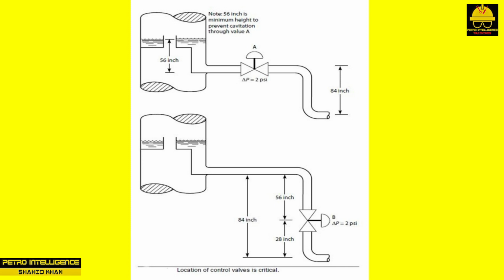If not, the water would begin flashing to steam as it experienced a pressure drop of 2 psi flowing across the control valve. The evolved steam would then choke the water flow, reducing the pressure drop across the control valve until the pressure drop equaled the depth, or head, of water in the draw-off sump.